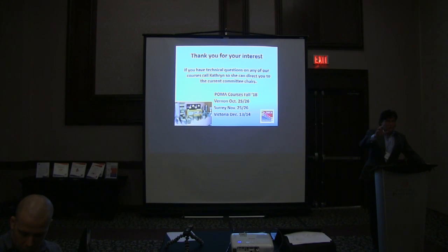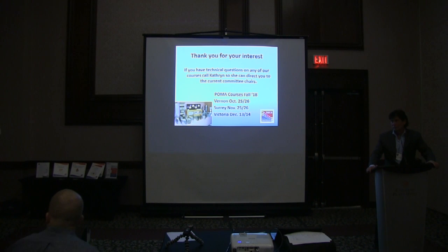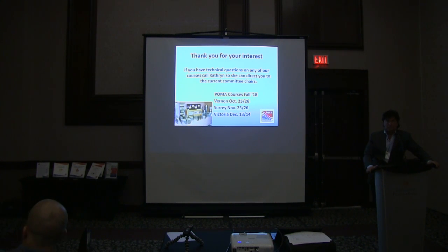Oh, one more question, sorry. What does that translate to in feet per minute? Multiply by 100, you get close. 10 miles an hour is 1,000 feet a minute. 5 miles an hour is roughly 500 feet a minute. All of our tables are based on branches at 500 and trunks at 1,000.